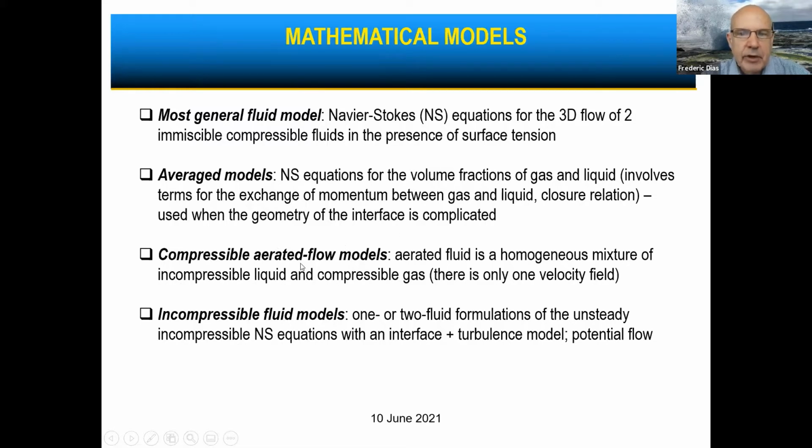Then there are the compressible aerated flow models, where the aerated fluid is a homogeneous mixture of incompressible liquid and compressible gas. The difference between the two is that there is only one velocity field as opposed to this one. And then the incompressible fluid models, one or two fluid formulations of the unsteady incompressible Navier-Stokes equations with an interface and a turbulence model. And then one special case, of course, is the potential flow.